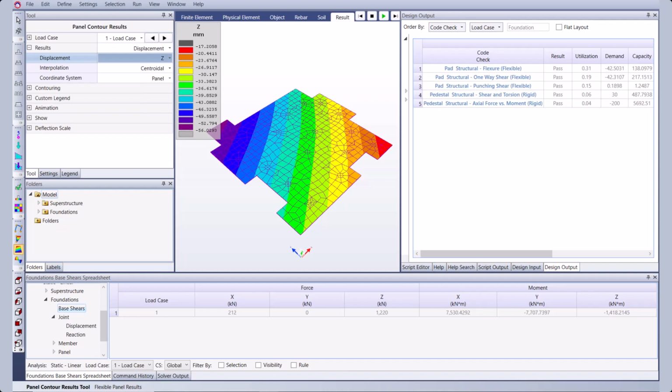If we think of the pile cap as, for example, a cardboard panel and our fingers as the column loads in the gravity direction in both cases, the model with higher stiffness would be sitting on the floor, while the model with the lower stiffness would be sitting on a pillow. The latter will undoubtedly suffer greater shear forces, as we just saw, because it is not supported on stiff soil, which also translates into a much higher one-way shear demand, resulting in the failing code check for this second example.